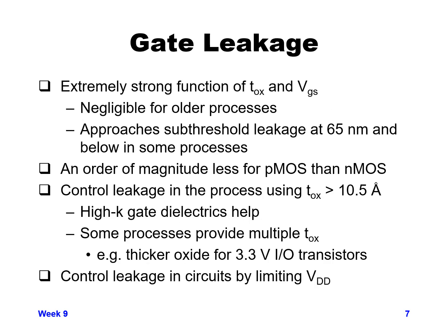As far as gate leakage goes, keep in mind that gate leakage is an extremely strong function of your oxide thickness and your gate to source voltage. Now, I mentioned many times in previous presentations, previous weeks, that the gate leakage was pretty negligible for older processes, and it's become stronger in more modern processes.